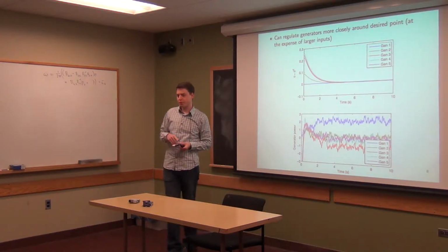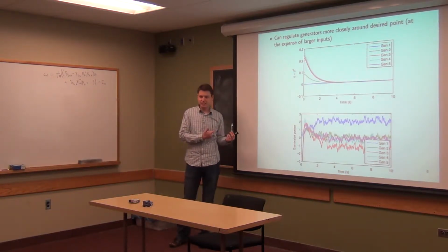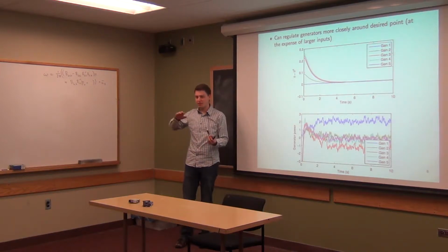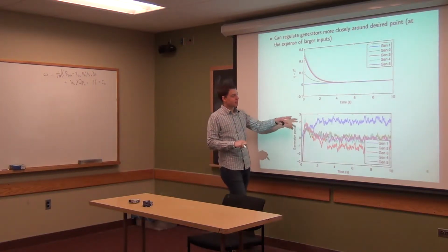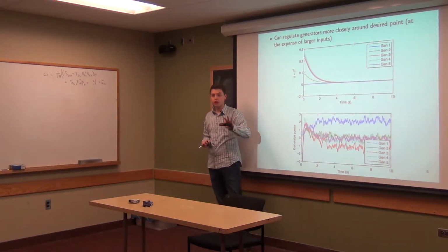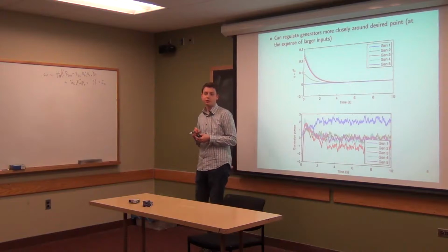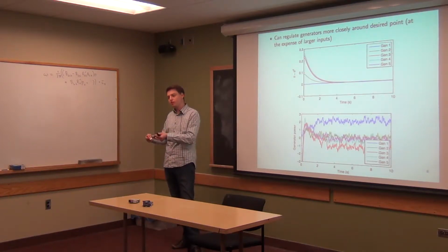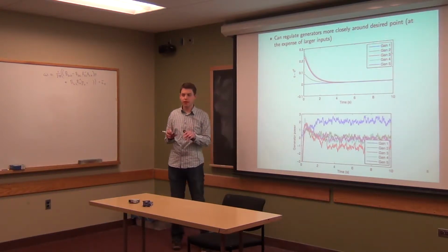The same, I should also add, goes for PD and PID control. You can get very similar behavior with PID control and with PD control for stochastic systems too. PID control actually can be kind of nasty in stochastic systems because its integrators can build up over time and swing back and forth a lot. But you can still take care of things like that as well. So the overall point is that these considerations apply both to PID control and to LQR control. The idea is that these methods do, in some sense, naturally account for a little bit of stochasticity because they are feedback methods, right? They're always telling you what to do based on the current state. So if the state deviates a little bit due to some noise, it'll push you back to the desired state. And so they both work well for that reason.